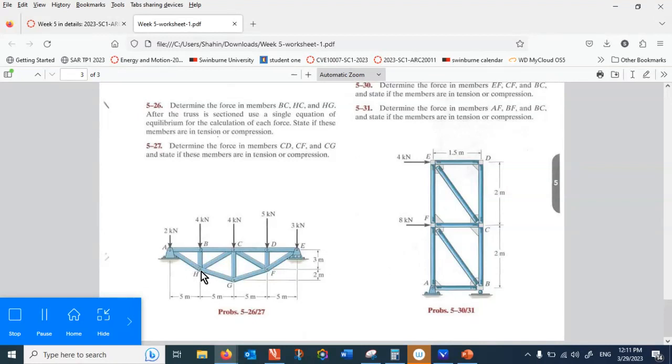So I give you a link. There is an Italian website which lets you solve the 2D truss structure. You build your truss over there, put the forces, and it calculates the forces for you. So we do the hand calculation, web calculation, and experimental measurement, and that gives you room to discuss the errors in the experiment, and that's the only thing. So here I only discuss the strategy, the steps.